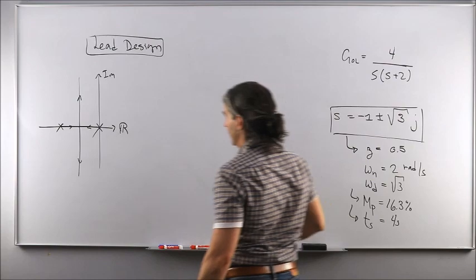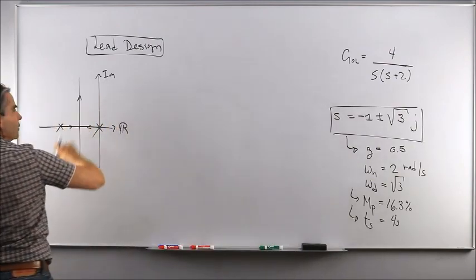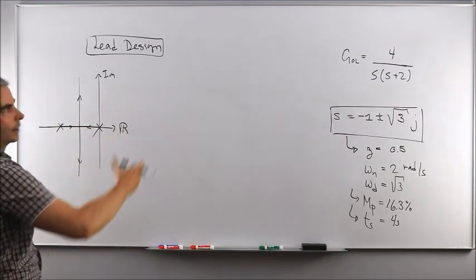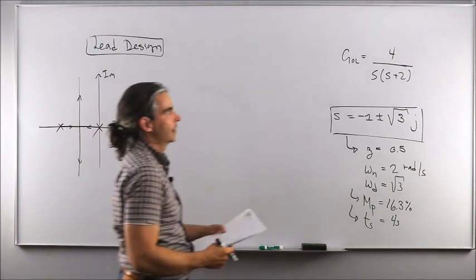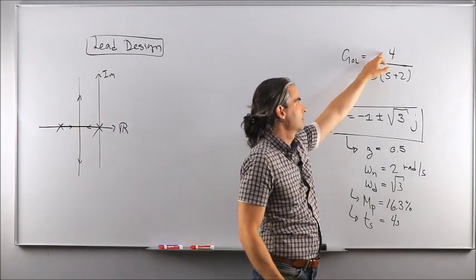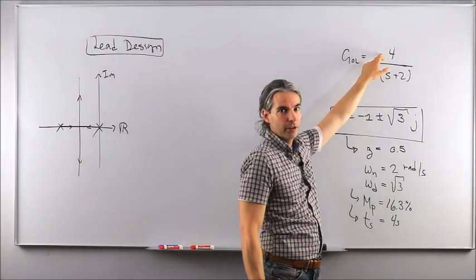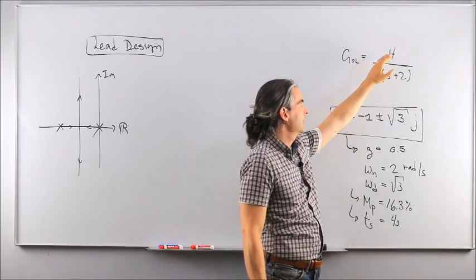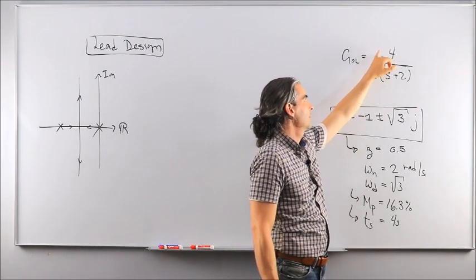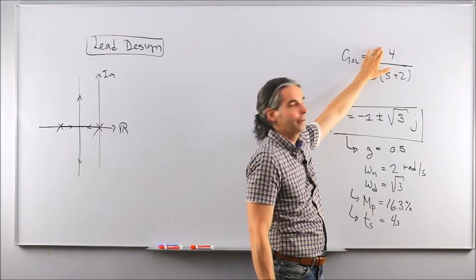But as this gain increases from 0 to infinity, you're going to get the closed loop pole locations. Okay? This is the meaning of a root locus for a given open loop transfer function that doesn't have a variable static gain, but has a specific value. Okay? So you always have to pretend that there is some sort of k variable that is going to multiply everything here.